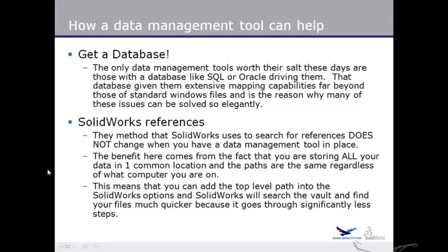Everybody is working off of the data management tool, which means that everybody is pulling from the same set of files. So if you go into SolidWorks and you set your SolidWorks file location options to that location, you're going to find these files a lot quicker because it's happening earlier in the algorithm rather than later.